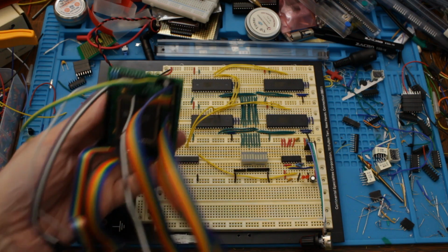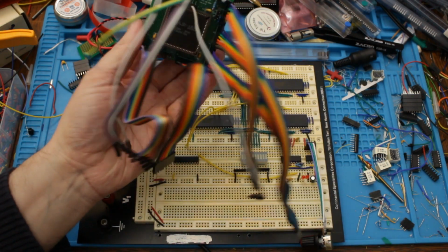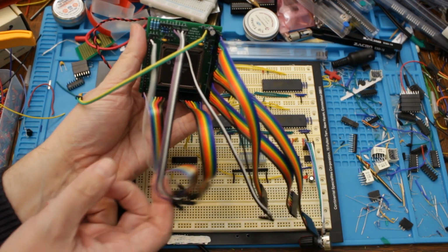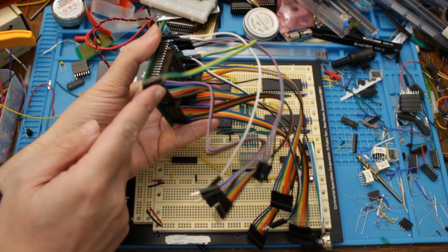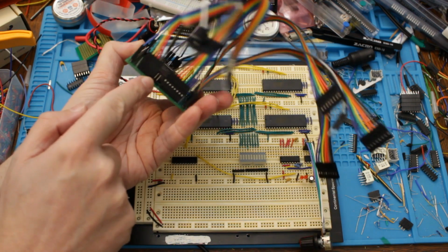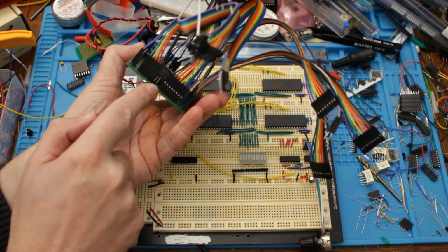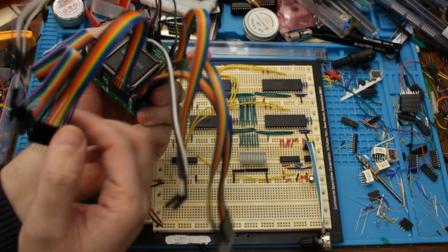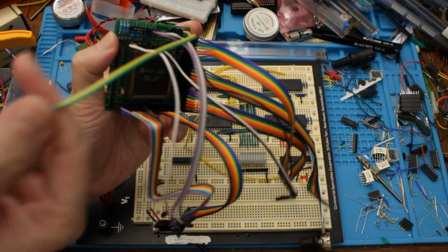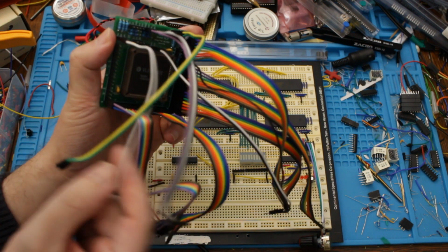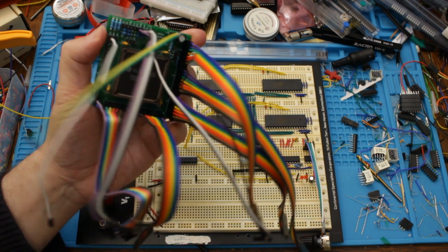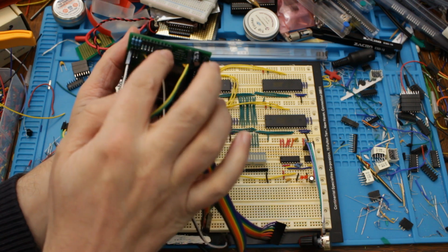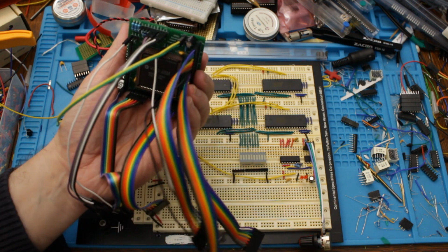I've also wired a lot of ribbon cables and things onto the ARM breakout board here. The address ribbon cable is attached here still, but as you can see, I left the bottom 2 pins off. And then we have 1, 2, 3, 4 ribbon cables of data bus, which are going to go to the ROMs. I have a power cable up here. This is the address latch enable cable. And then various control signals coming from the top of the board here. Oh, and the clock, obviously.